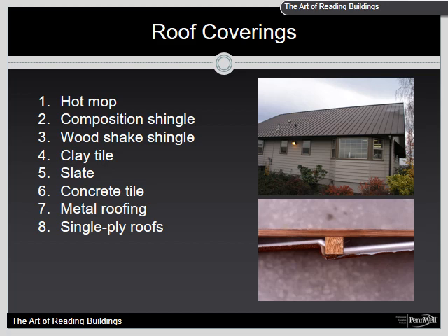One of the problems with this type of roofing material is that once they begin to leak, a lot of times individuals, rather than paying to have them removed like they're supposed to, will go ahead and slap on 2 or even 3 layers, depending on the age of the roof, of this shingle material, or composition shingle, as they call it. Again, the problem with that is the added weight to the roof, as well as making it more difficult to ventilate the structure during a fire.